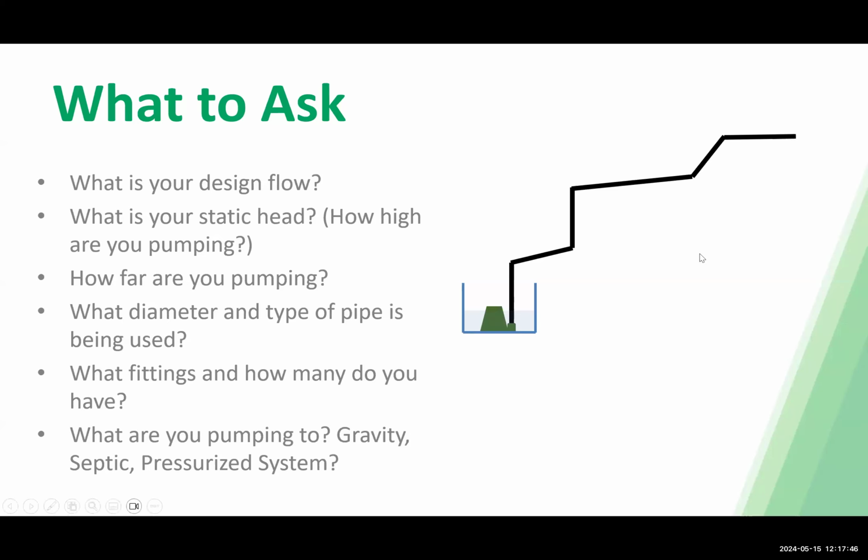So, continuing on what to ask, you need to know what your design flow is. That will typically be in gallons per minute or liters per second. You need to know what your static head is. So this is going to be how high are you pumping? Are you pumping 10 feet or are you pumping up 50 feet? That's going to put a lot of pressure on your pump.